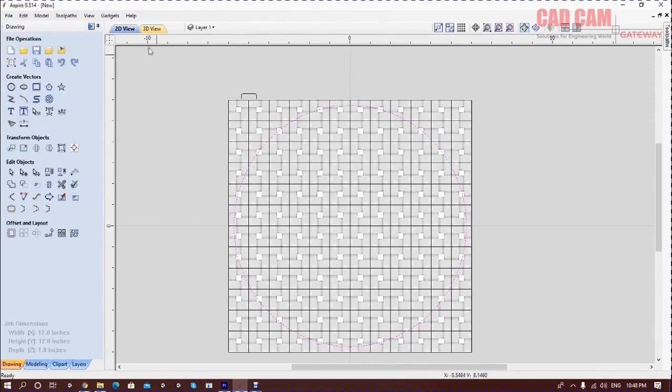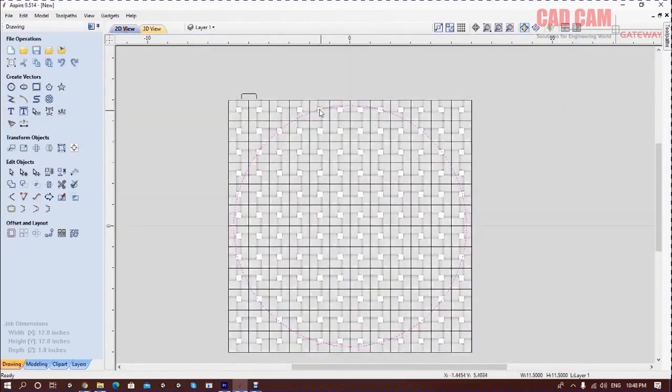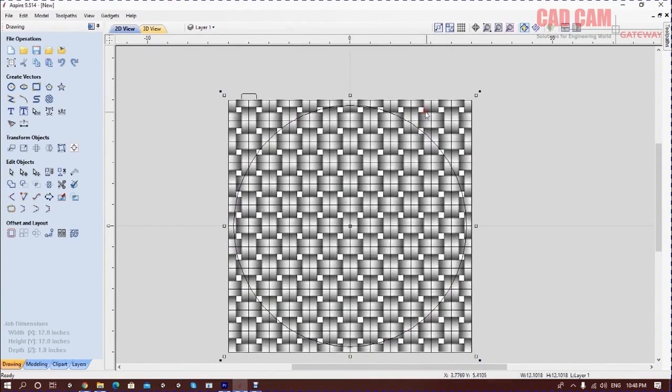All right, so here, this is our complete view for now. We have just designed a boundary for the area we want to cut. So how are we going to manage this boundary that we have just created? See, here I have selected this 3D object, and while holding Shift, select the 3D object, and with Shift, you also need to select this circle or the selected item that you want to use for trimming.